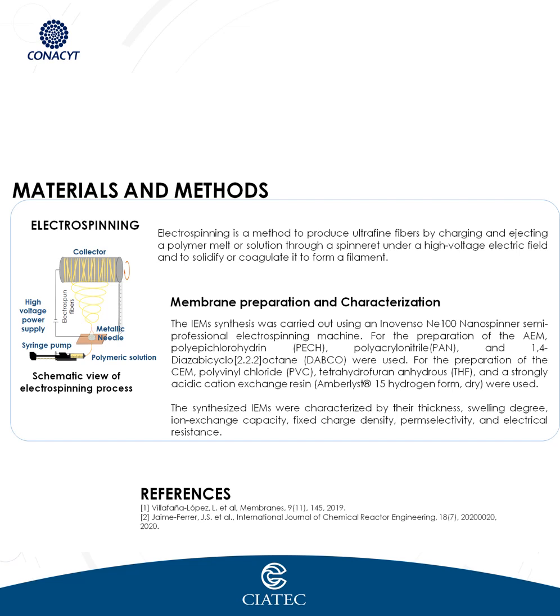Electrospinning is a technique where a polymer solution is forced through a nozzle that has a specific voltage applied. These electrospun materials show unique characteristics due to their nano-size structure, large specific surface area, and tunable porosity and wettability. The nanofiber properties and the overall membrane performance can be improved by controlling the fiber diameter, surface morphology, and the internal structure of the nanofibers.